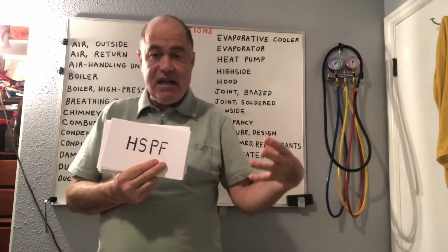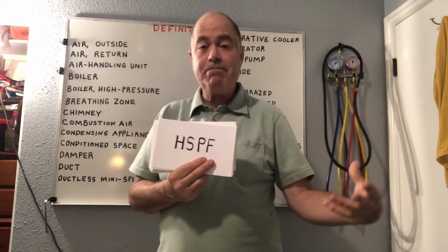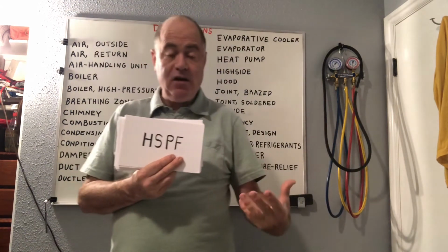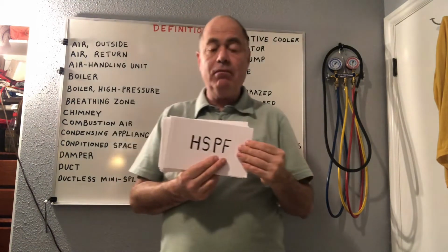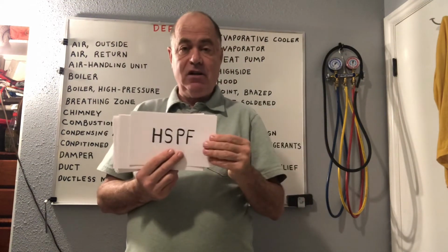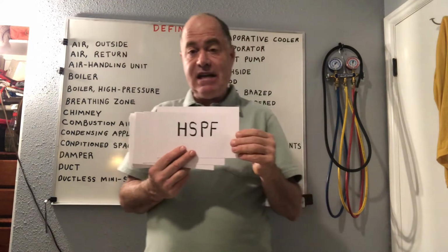And then this is HSPF, or Heating Seasonal Performance Factor. This is how we rate the heating portion of a heat pump to see how efficient it is. And again, very similar to SEER. The higher the number, the more energy efficient that heat pump's heating is.